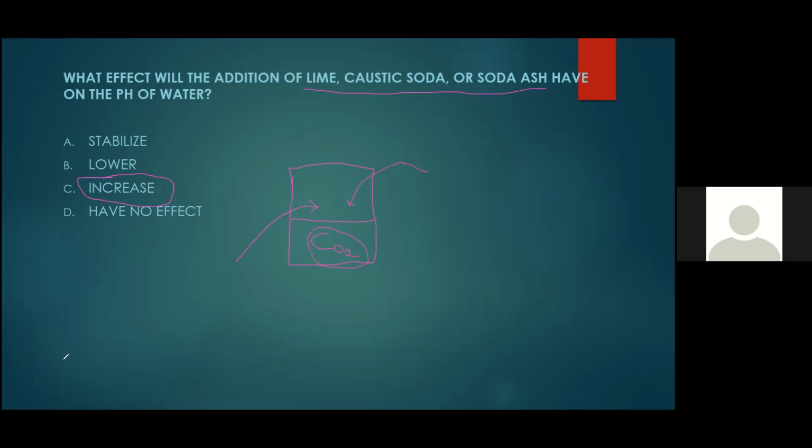Now I saw the word muriatic acid on there. And that's another one that's quite widely used in water treatment plants. They use a liquid muriatic acid, and that will bring pH down. It's difficult to use because you have to handle an acid. So bigger, larger water treatment plants will add carbon dioxide. They'll bubble it in, right?